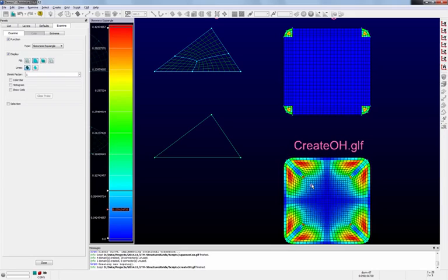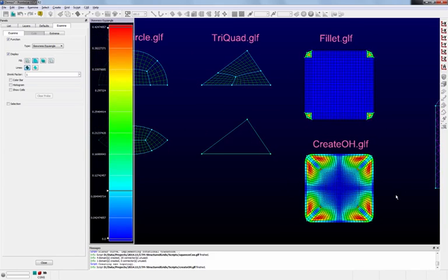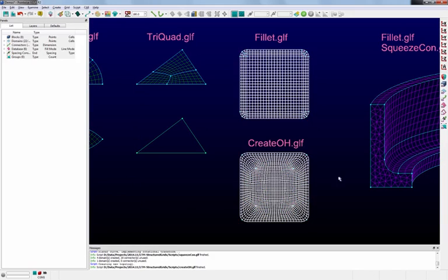So it really depends on your particular circumstance, what you're trying to get after. If you can afford this additional topology here, you can wind up with a higher quality grid overall and confine the problem areas to a very small local point. Or you can use a larger global script that will produce fine results. Again, it's a matter of balancing your cell quality and your solution accuracy.